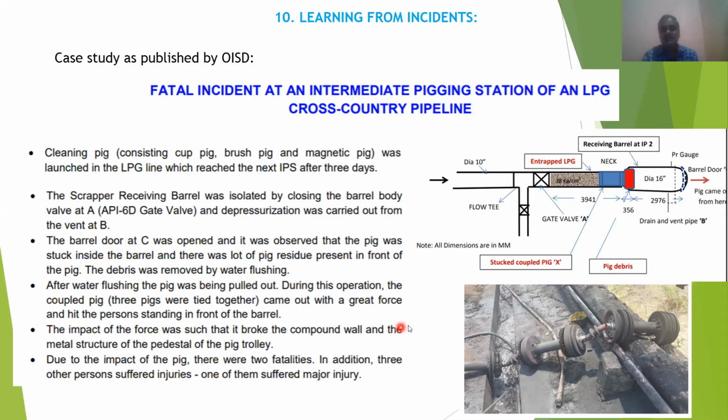So my friends, this is the barrel door. Never stand in front of the barrel door. Always stay away from the barrel door during pigging operation. Or do not stand in front of any flanges, bolted doors, anything. It is quite normal in the operating conditions. Many people will use homemade receivers, homemade launchers with a small pipe and all, thinking nothing will happen. It will happen, my friend. Some cases are like this. So ensure that you are working safely.